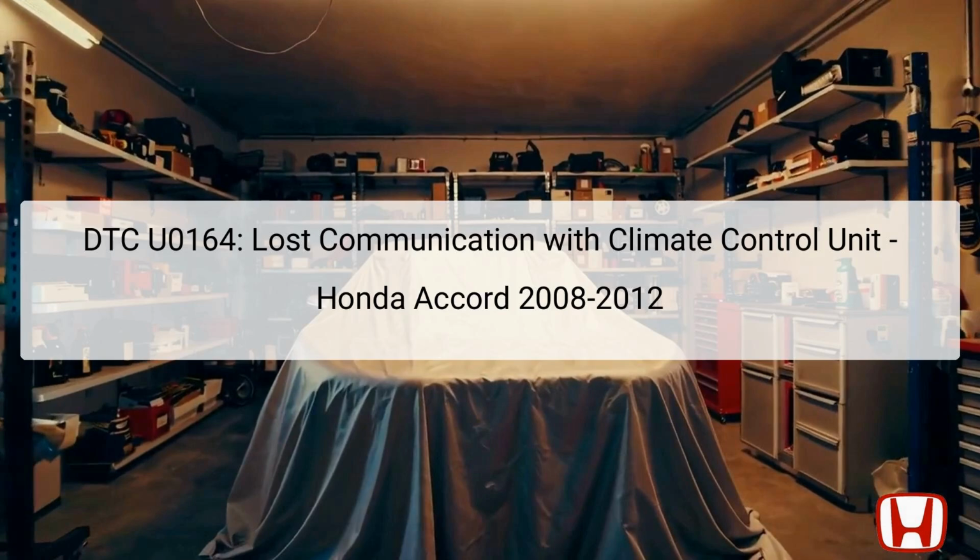The Diagnostic Trouble Code, DTC U0164, indicates a communication failure between the door multiplex control unit and the climate control unit in the Honda Accord models from 2008 to 2012. This code often arises when the climate control unit cannot receive or send necessary signals that are crucial for regulating the vehicle's heating and air conditioning systems.